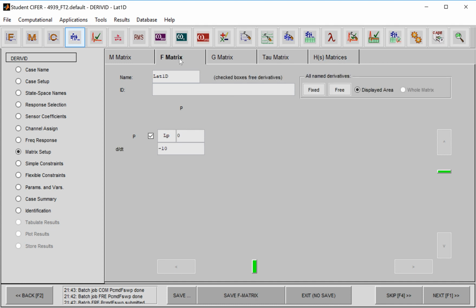It is worth stressing that there's only one LP and L delta A for each airspeed. Assuming nothing changes with the aircraft, LP and L delta A are fixed for each airspeed. In the case that you non-dimensionalize it, if you computed CLP, then for the most part that should be almost invariant over airspeed. So when you're doing multiple calculations, you're running derivative multiple times to try to get these parameters, LP and L delta A.